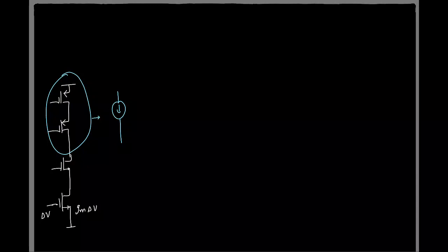And this fellow basically is supposed to behave like a current source. That's all you wanted. Okay, so here if you see, this is basically in which kind of configuration? I mean, there are three configurations: common source, common drain, common gate. What is this? Common source, okay. And this is a current buffer. It's a common gate, right? And this is how we are making the cascode, putting the common source and common gate together, right? And in this example, we see that common source is made using an NMOS. And same is the case with the common gate, right?